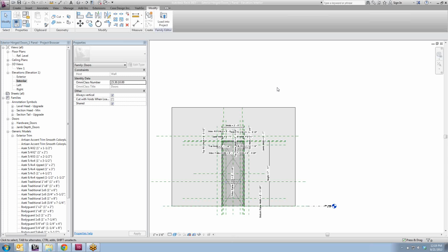Quick question though, are we still building the connector with a full 2x4 wall on the outside of the mod wall? I've been told to just put a drywall only wall there because they can just attach that right to the sheathing on the outside.